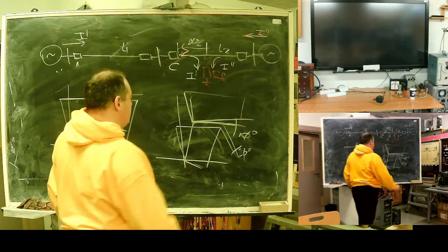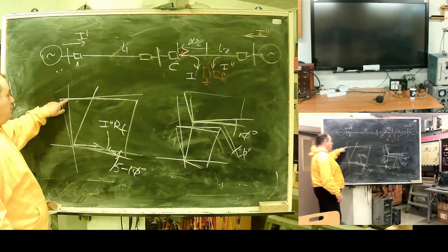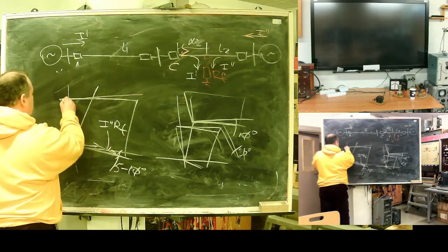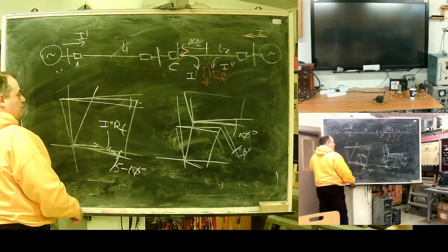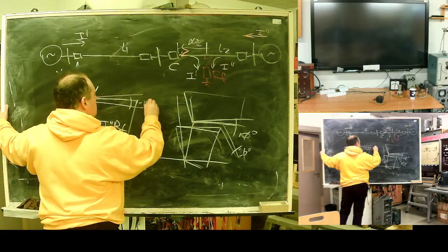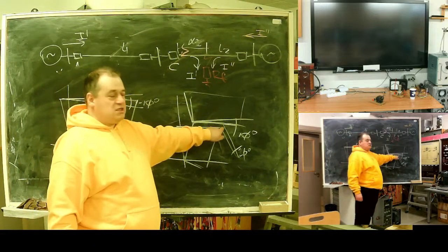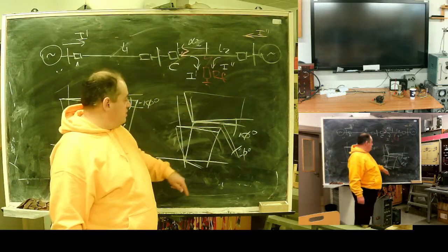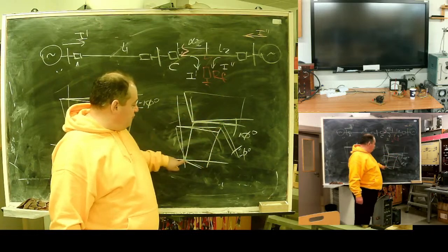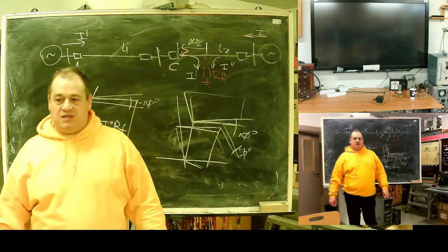But for 20%, you will be forced to tilt the upper border. To ensure 20%, you will need a negative angle, let's say minus 10 degrees. If the device allows you, you can reduce this margin to 10%. But you need to check this point. It's your first zone. It's the lower border of the next protection. It's important.